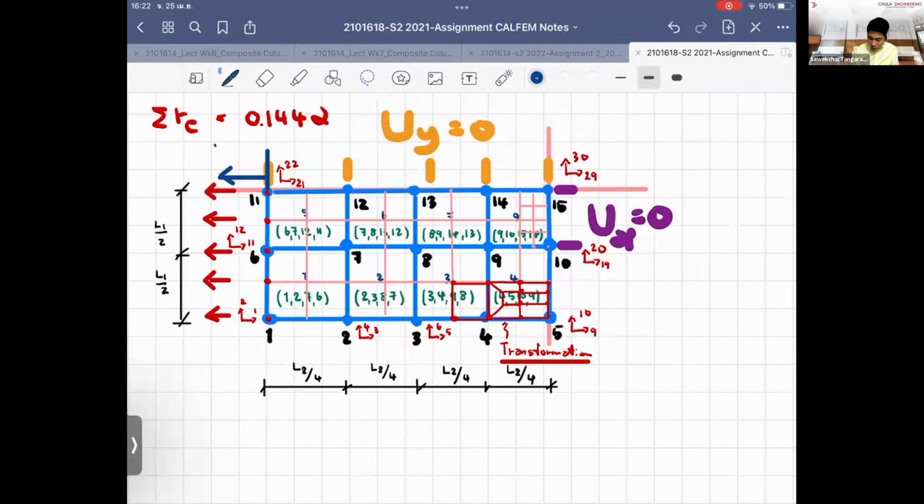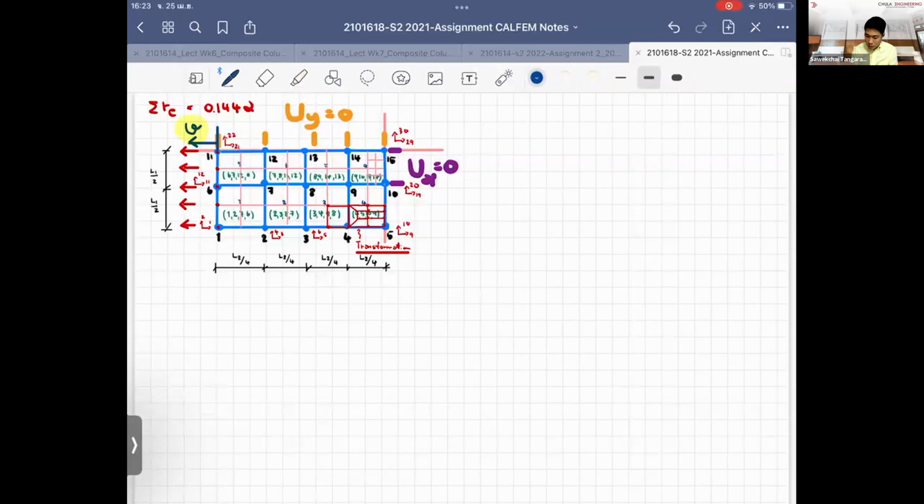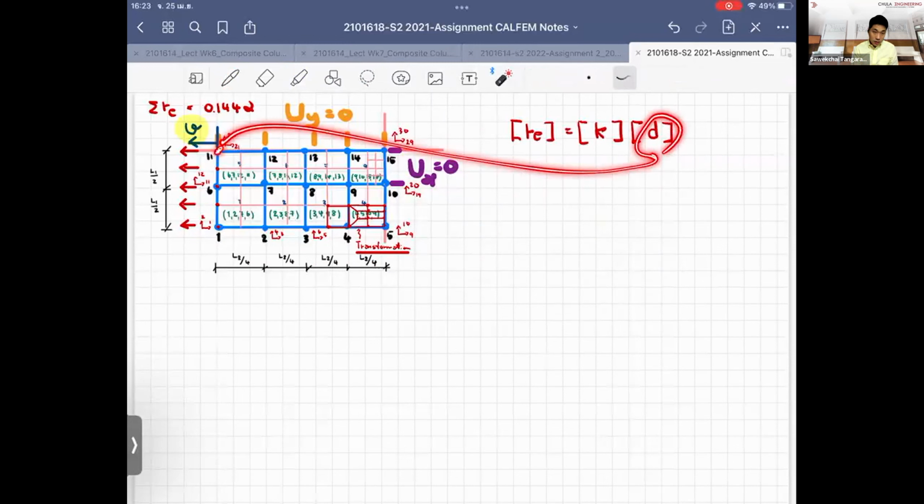We'd like to know how much of the displacement, but every time when you discretize an element, you use the information, which is the vector R equal to the K matrix times G, and you obtain the value of G, which is the displacement, and you just extract the displacement associated with the degree of freedom, and this is the lateral displacement.